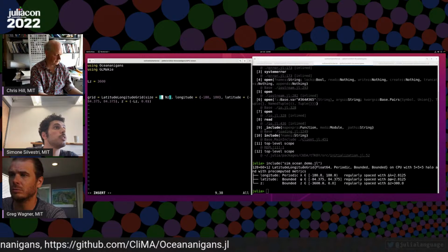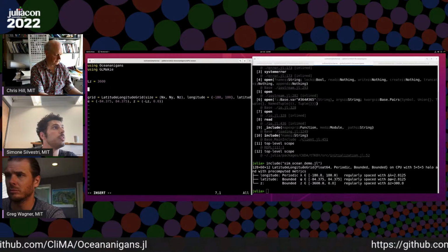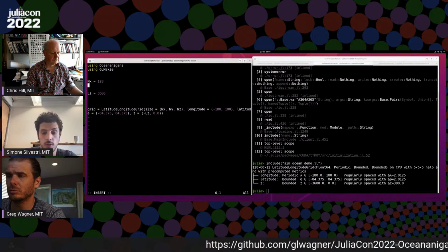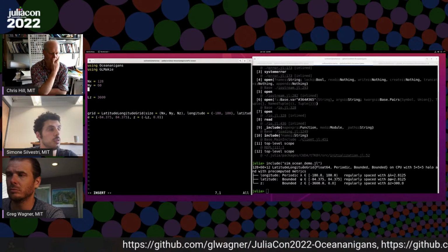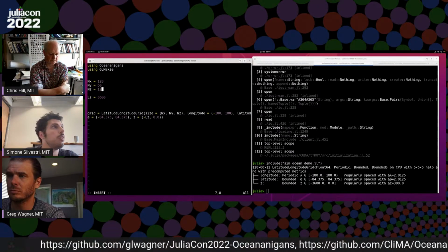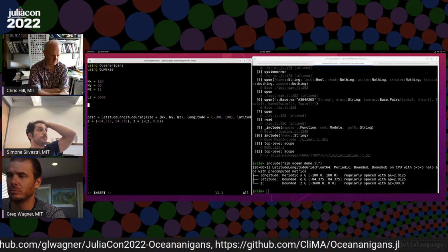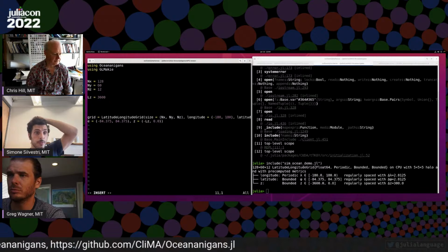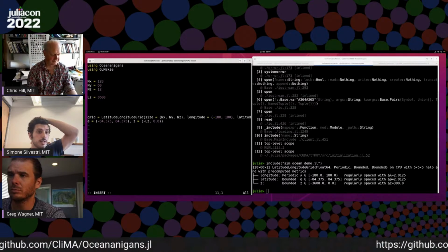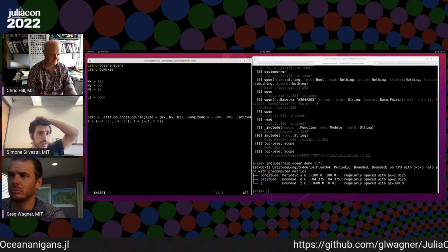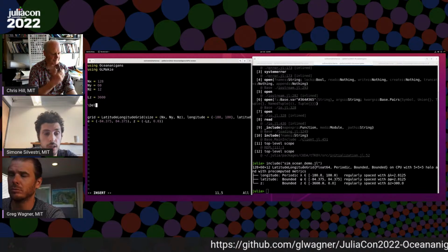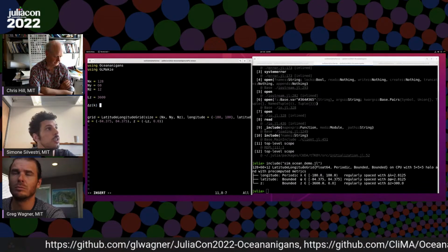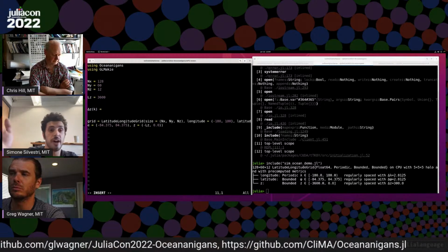So let's start by giving some parameters here to make it a little bit easier to work with. 12. To make a grid in Oceananigans stretched in one direction, you can pass it either an array or a function of the index. In this case, I've already defined a function which works, but you can define whatever kind of function.